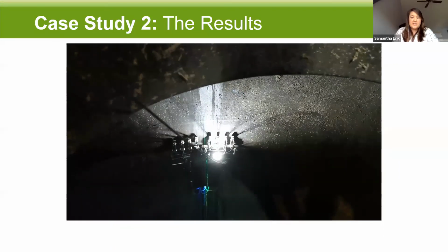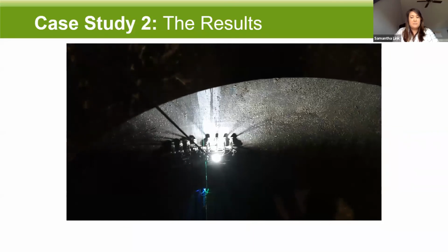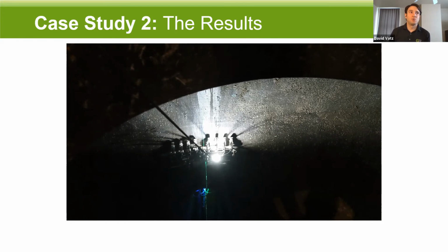Have you ever scanned blow line from digesters to blow tank? Yes. The robot can do piping down to about 6 inches, so we can scan blow lines. We've done blow lines. Specifically, the robot can handle the radiuses as long as they're about a 6-foot radius, which is what we're seeing coming out of the bottom of most batch digesters. So yes, we can absolutely do blow lines.